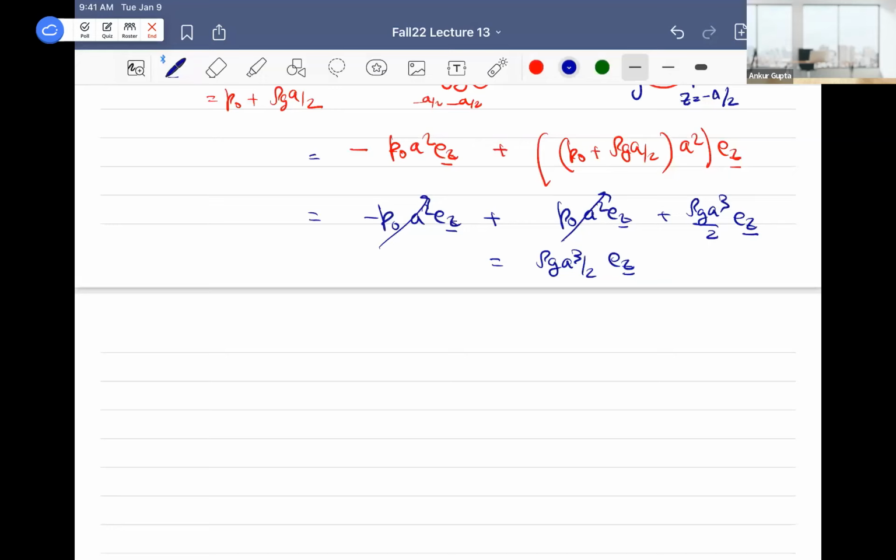But I think as a practice, we're doing it this way. But yes, that is actually the derivation of Archimedes principle on an arbitrary shape. The book has that, but we don't follow it in practice. In your homework problem, obviously the intention is to calculate the pressure force because that's the habit we want to build. But yes, at the end the answer has to match.